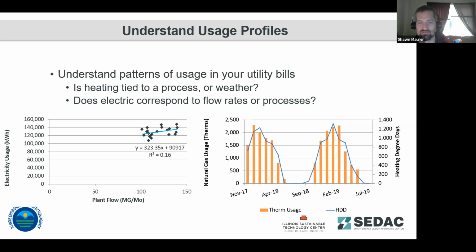Usually that correlation is pretty strong, ties to weather. So that's what you're seeing on that chart there. It's a comparison of gas consumption to heating degree days. And this kind of gives us an idea of how well insulated your building is, what kind of impact and efficiency your HVAC systems have on your overall energy consumption.